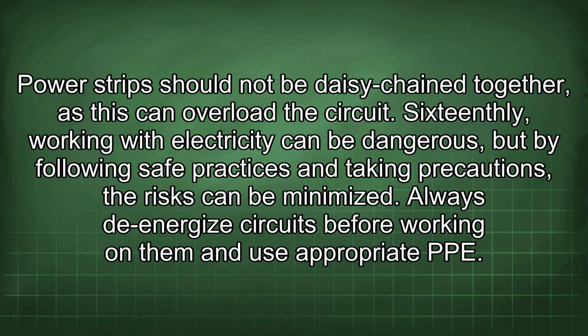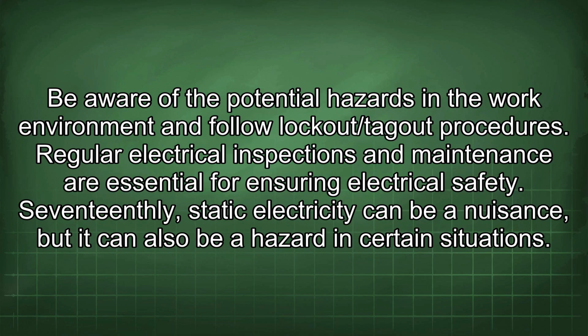Sixteenth, working with electricity can be dangerous, but by following safe practices and taking precautions, the risks can be minimized. Always de-energize circuits before working on them and use appropriate PPE. Be aware of the potential hazards in the work environment and follow lockout/tagout procedures. Regular electrical inspections and maintenance are essential for ensuring electrical safety.